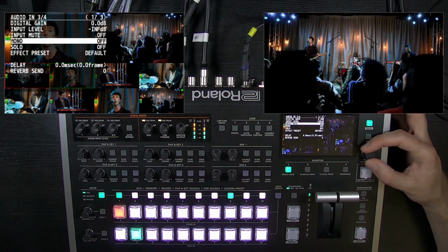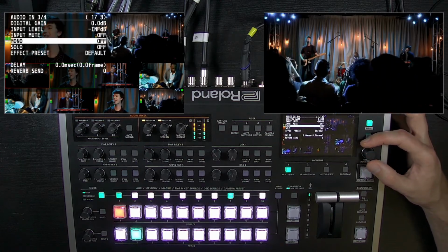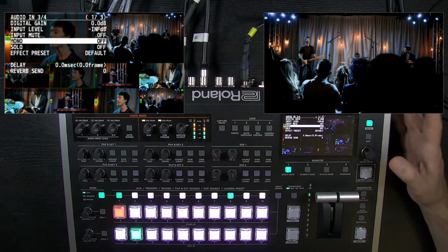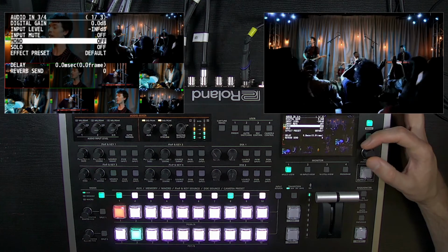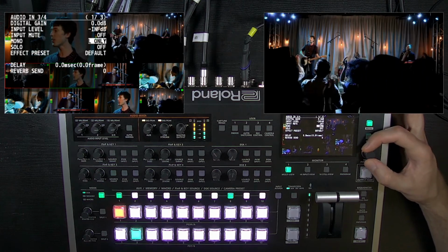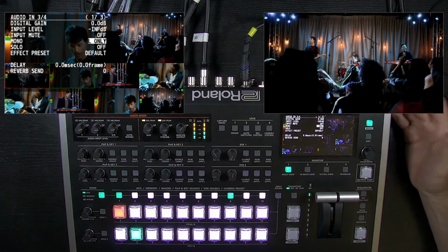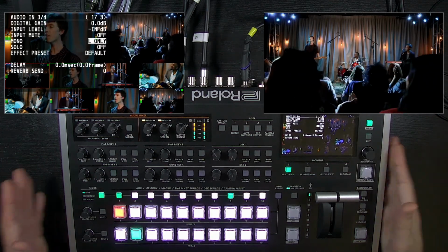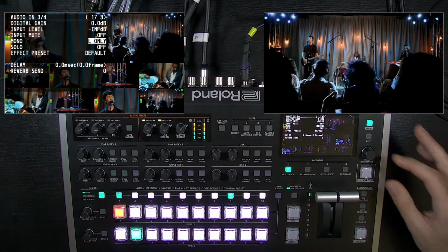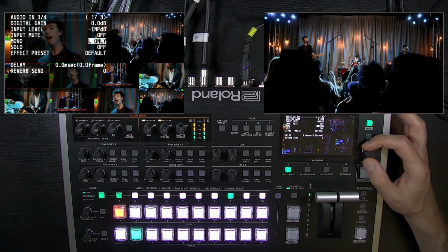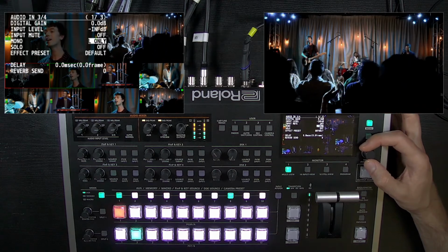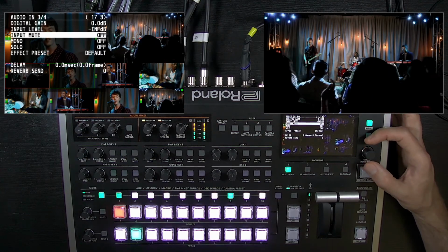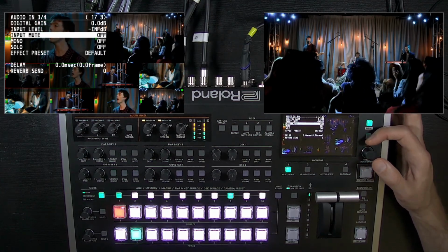And then audio in 3 and 4, this is the RCA in. With these stereo channels, the RCA in is one of the stereo channels, and each embedded audio input is a stereo channel. You have a mono switch, and this can help if you have a camera that has a microphone connected to it, and on your V160 mix, you hear it on the hard left channel. You can set it to left only for that embedded input and center it mono, or you can sum the left and the right. A very helpful tool to keep all the dialogue centered in your mix.